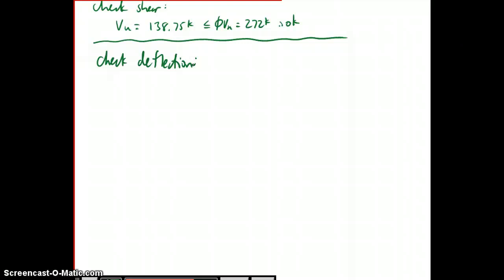So one way to make an assumption that makes it easier for us to solve deflection by hand is to take a look at the total load being applied on this beam. We have 20 kips per foot across the far right 6 feet, and we have 5 kips per foot applied on the leftmost 18 feet. That's a total of 210 kips.